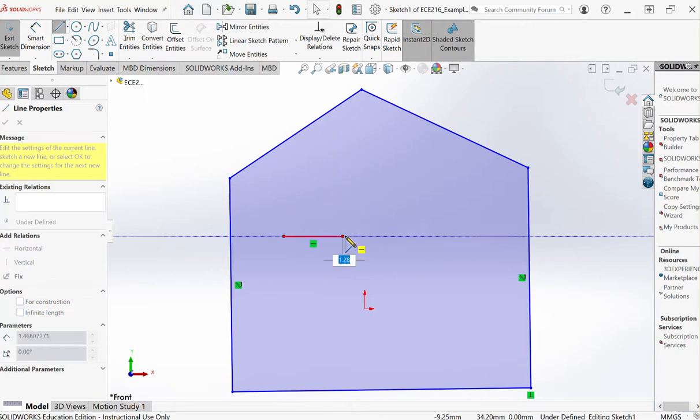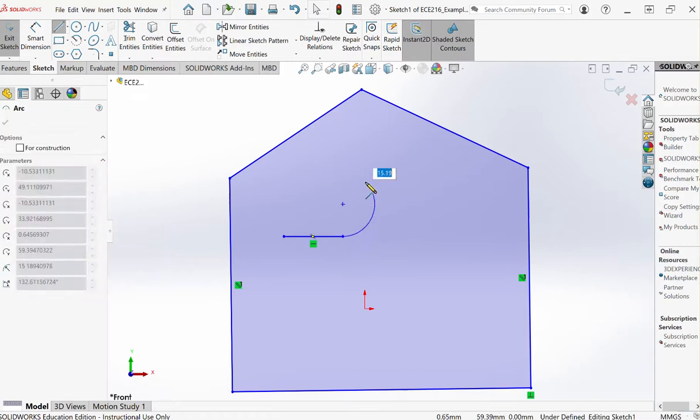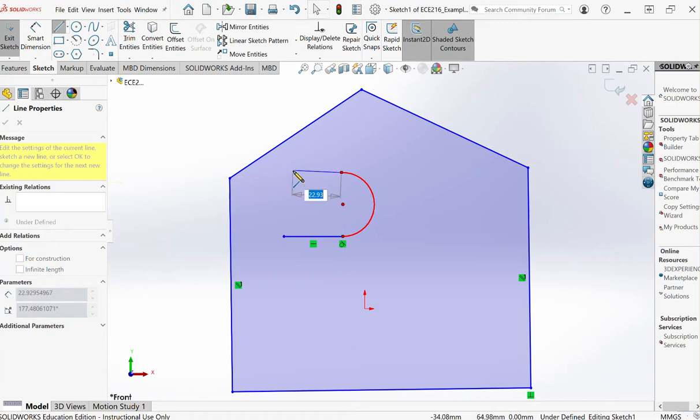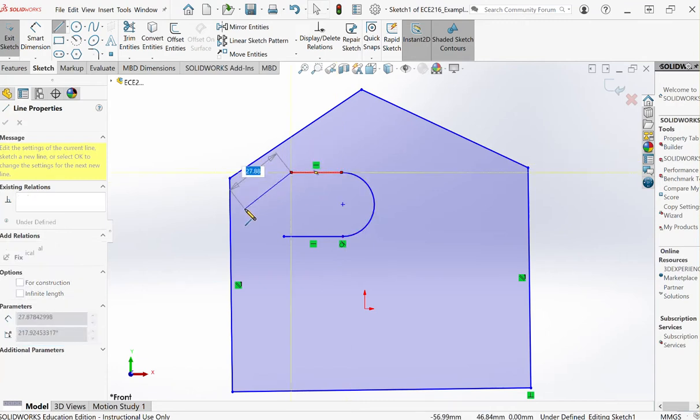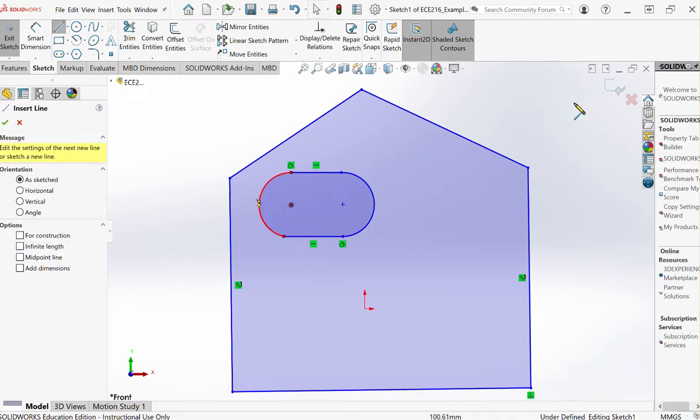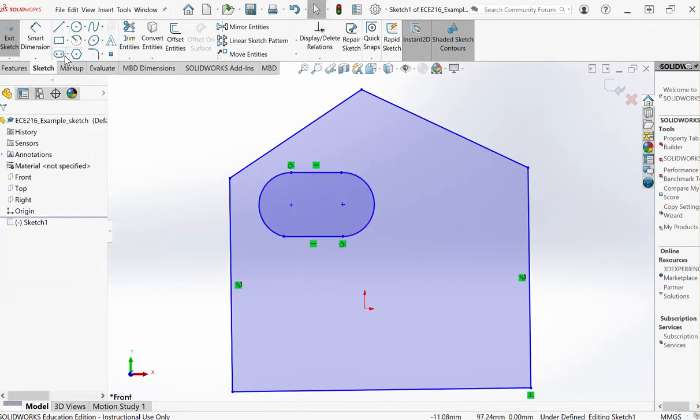But if I come back on the point, you see, I have a little circle there. So now what I'm drawing is a circle. If I keep going, I do a line. But if I come back, now I'm doing a circle, and I can click there. I know you can do this shape with the straight slot or different slots that are available, but there is a way to do arcs of circles and lines without removing your mouse from your sketch.